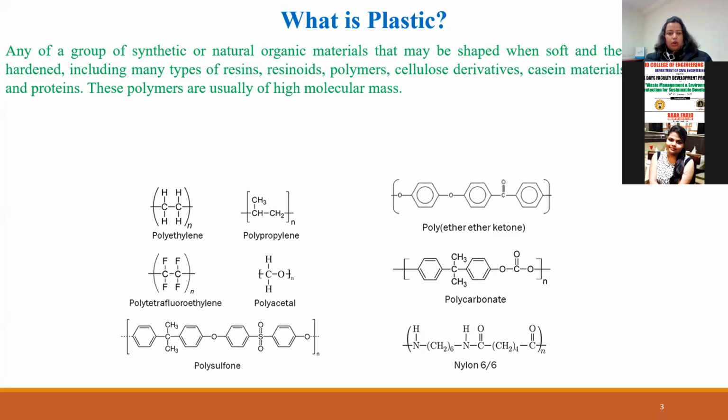Amongst this entire spectrum of plastic wastes, we have to select a few which easily disintegrate, which can be easily shredded, which share the chemical properties of the bitumen so that they can be mixed with bitumen in a better manner. Because if they are not on the same page with the properties of bitumen chemically, they might not blend well, and we really want them to blend well.